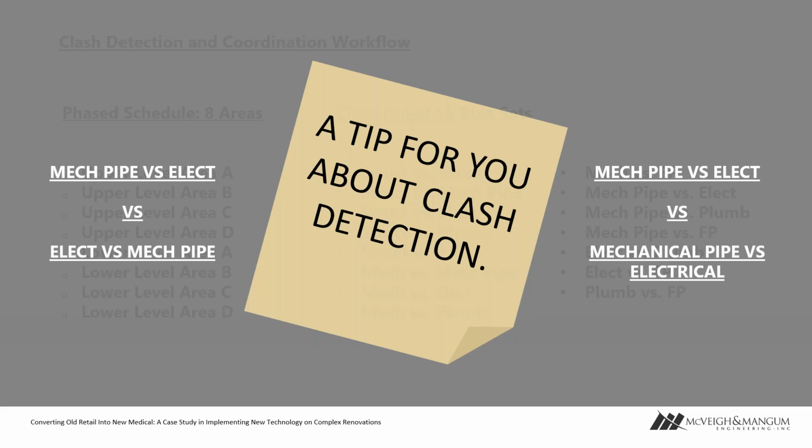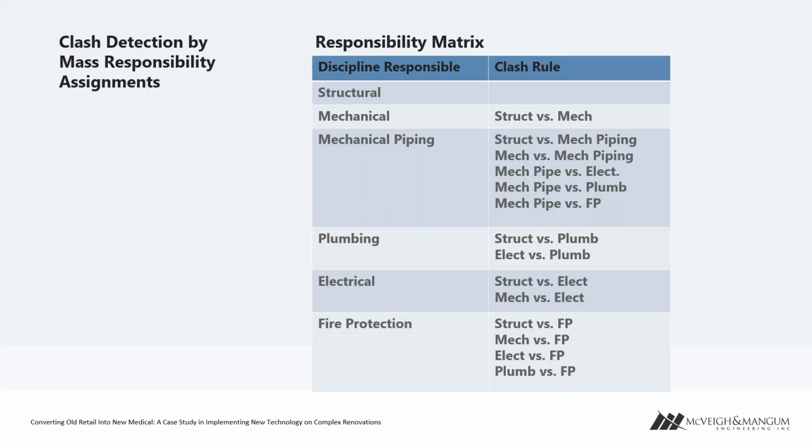So if you write out plumbing the full word, or you just do PLUM, you have to establish that, because as you get down the road, as you get into the projects, you're going to populate a lot of issues and then realize that they're not coordinating with each other, they're not being filtered correctly, and you're starting to lose the leverage of BIMTrack.